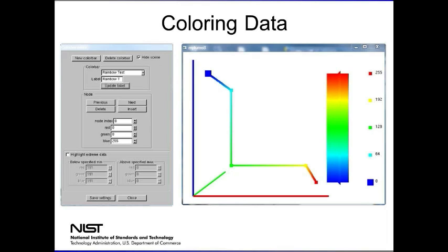In the new version of Smokeview, there's a capability of creating your own color bar. You don't have to use the one that's the default. Basically, for those of you familiar with tours, it's very similar in idea to creating a tour that goes through the scene, in that you've got 3 coordinates, red, green, and blue, which I'm representing as 3 coordinate axes.